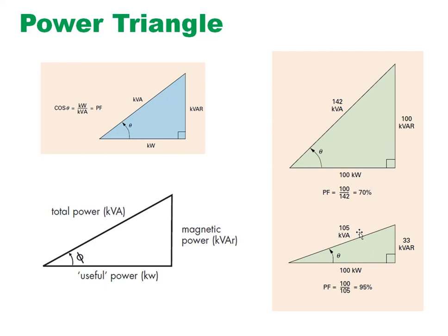is sufficient. Correct? So what are the methods to reduce the reactive power? What are the causes of that reactive power, and what are the various ways to reduce it? That we have to see. Then we can improve the power factor from 0.7 to 0.95.